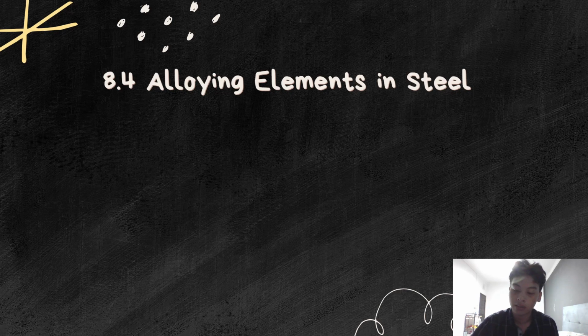Chromium is generally added to steel to increase resistance to corrosion and oxidation, to increase hardenability, to improve high temperature strength, or to improve abrasion resistance in high carbon compositions. Nickel, when used as an alloying element in constructional steels, is a strong strengthener. Molybdenum, vanadium, niobium, aluminium, titanium, boron, tungsten, zirconium, calcium, cerium, lead, bismuth, nitrogen, phosphorus, sulfur, hydrogen, tin, arsenic, and antimony.